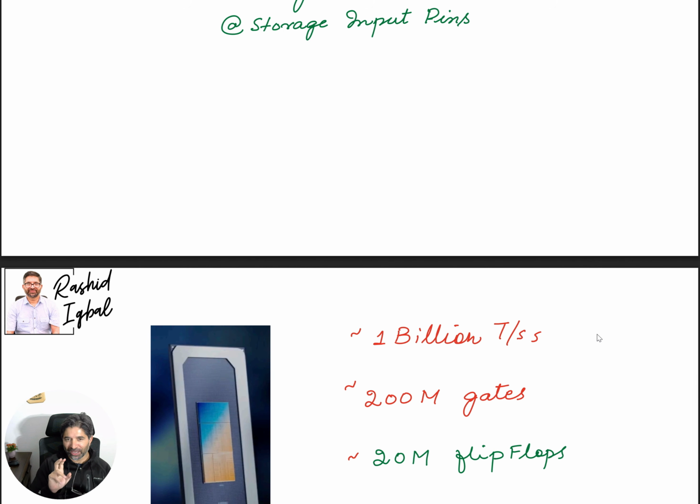It's very hard to make exact numbers because foundries are a little different, and within each foundry you have different densities available. So think of a NAND gate as 0.03 square micron, and that translates into a chip containing 1 billion transistors. You don't need that much area. If you think of 2% utilization, probably maybe 15 mm square, something like that, just rough numbers.